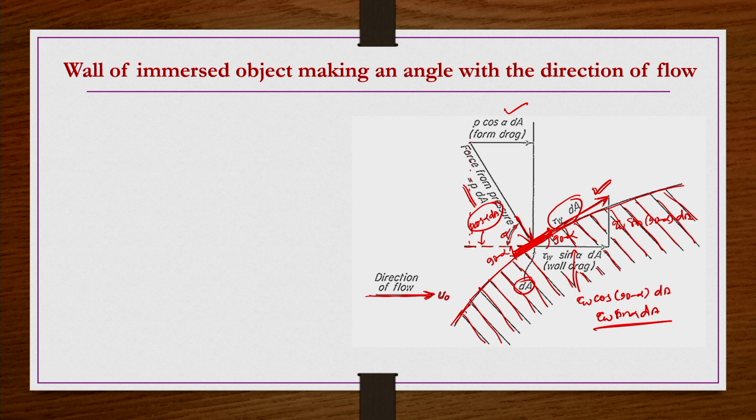Remember, if the geometry orientation changes or the entire geometry changes, let us say if you have a geometry like this, then things may be very different, right. Geometry and its orientation, if you have an irregular particle like this, not only geometry, its orientation is also going to have an influence. So, for a given geometry one has to evaluate the respective pressure and viscous drag components, then do the calculation accordingly.